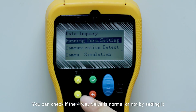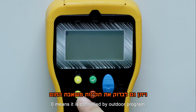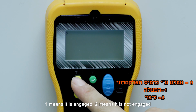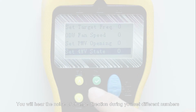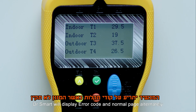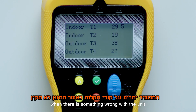You can check if the 4-way valve is normal or not by setting it. 0 means it's controlled by outdoor program, 1 means it is engaged, 2 means it is not engaged. You will hear the noise of change of direction while you set different numbers. Like LNS connection, Dr. Smart will display error code and normal page alternately when there is something wrong with the unit.